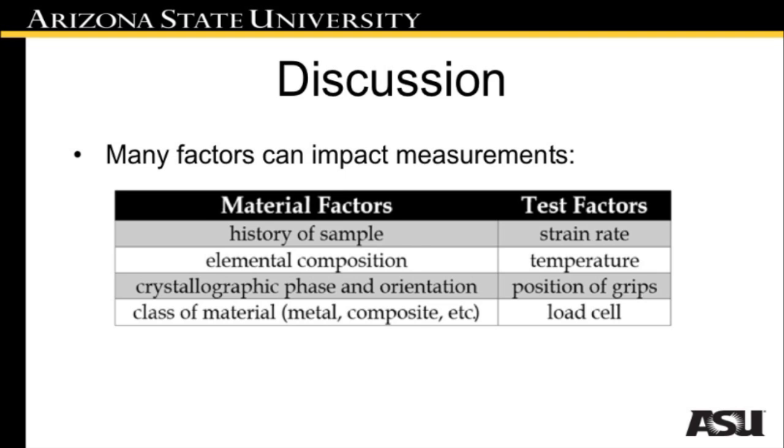The exact mechanism for this behavior is material dependent, but one common reason is because the atoms have more time to rearrange themselves. This is why you can slowly pull silly putty and it will stretch an enormous amount before it breaks. However, if you pull on it quickly, it will tear immediately. This is important to consider when designing components. For instance, if a load is applied over a large amount of time, the part may be able to absorb the energy, but if it undergoes a sudden collision, it may shatter instead.